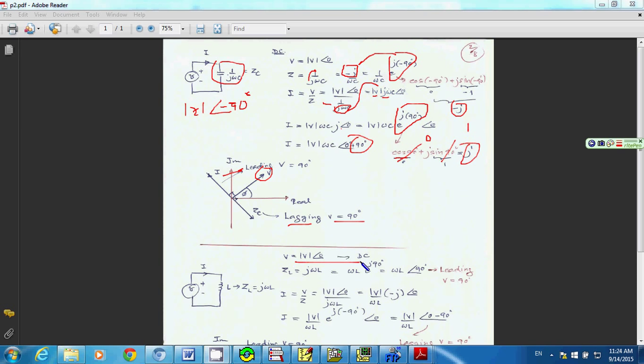If you understand the basic idea, let's move to our inductor here. You do the same thing. Analyze the DC voltage source. Your ZL, the impedance of your inductor, is equal to j omega L, and then you can write j as exponential j 90 degrees. And that's why you have the leading phase compared to the voltage of 90 degrees. This is for the impedance of the inductor. But if you take a look at the impedance of the capacitor, you can see that it is lagging, or behind, the phase of the voltage by 90 degrees. So that's the difference. It works out perfectly.